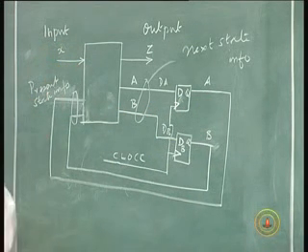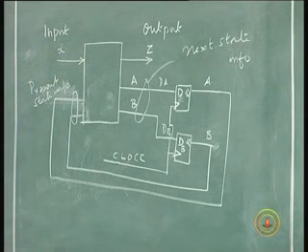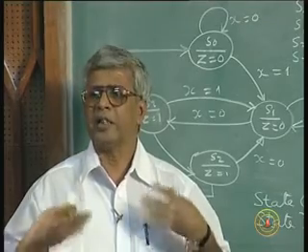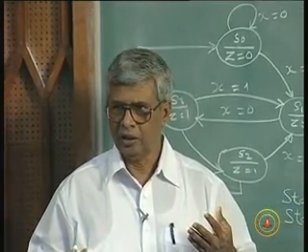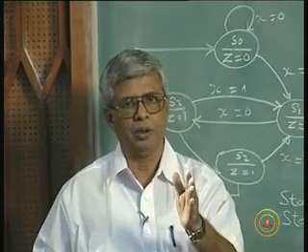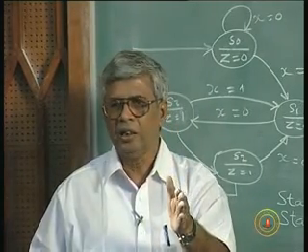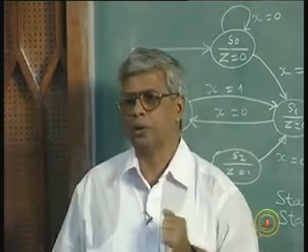So for one clock period the circuit is in one state. It is not necessary that the circuit has to change state. If x is 0 for a long time, for several clock cycles, and the circuit happens to be in S0 and x is 0, it will remain in state S0, right? Every clock pulse it will sample the input. During every clock transition, the input will be looked at. It's called sampling the input.